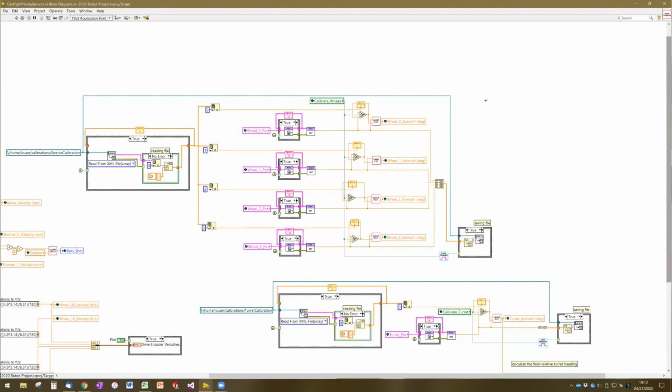So field-oriented is the first one that you described, where if you press forward on the joystick, you're always going to go away from the driver. And if you press backwards on the joystick, you're always going to come back towards the driver, regardless of the orientation of the robot. And then robot-oriented would be you're always going to go forward relative to the forward direction on the robot. So as Ethan said, if you rotate the robot 90 degrees and you press forward, the robot would go, I guess, to your left, which would be the forward direction relative to the robot.